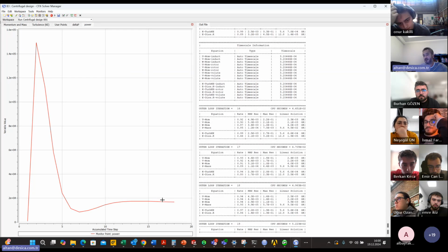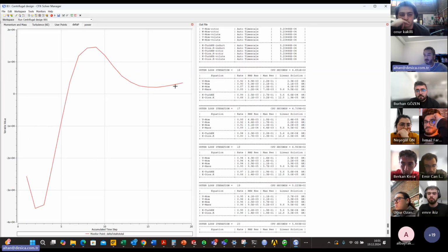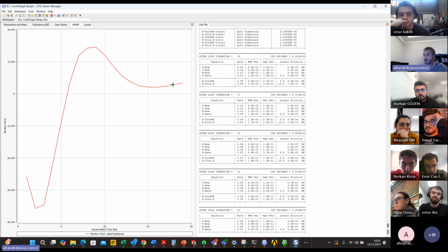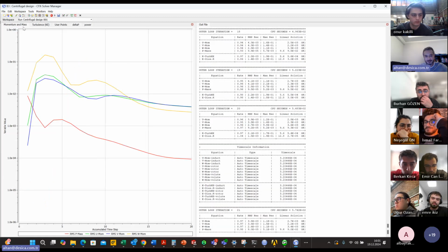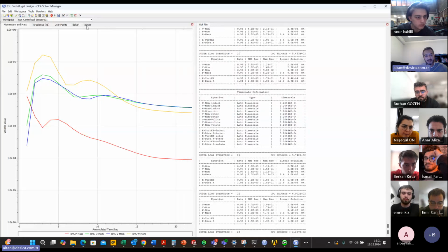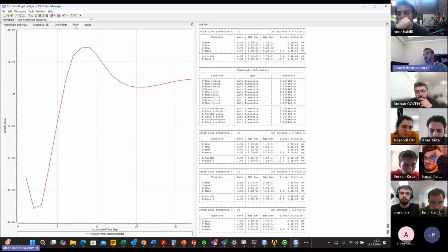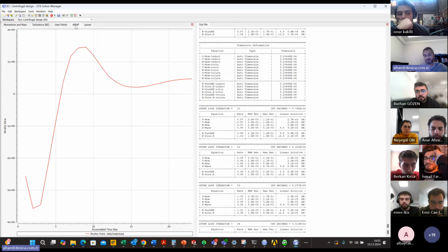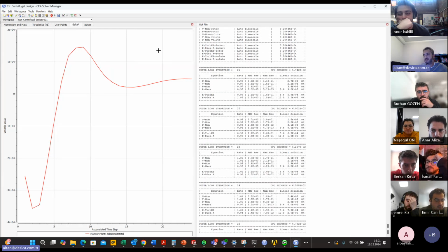That's why we perform the simulation. We should get the power level and we should get the delta pressure level. So following these values is more meaningful for the convergence decision. Okay, because this residual may stay high because of some recirculation zone and so on. But if delta pressure is stable, then you can assume your simulation has converged. Okay. This is for the radial one, and for the axial one,